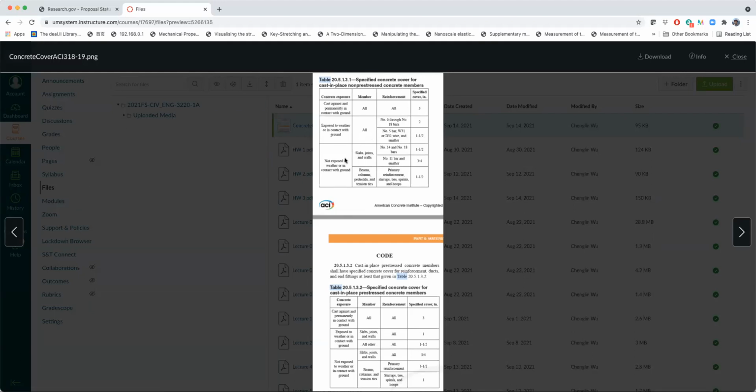Okay. I was just confused because the other table said the clear cover had to be like 1.5 inches. Right, I provided 2 just for safety purposes. I think we have enough beam width anyway, because the table is 8 inch, and we have 12. It's much higher than the number. So I just threw in the 2. I think that's going to be fine. But to be sure, you can take a look at the table.